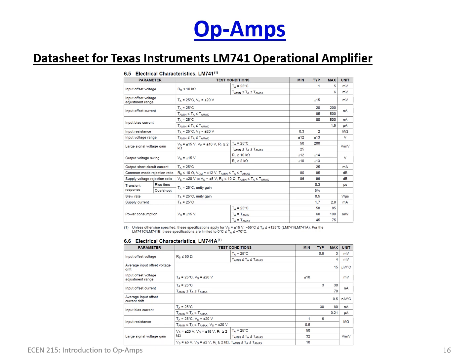Now, one thing I wanted to show you here, the interesting thing, and I'll blow it up here, is your input resistance. We talked about that a moment ago. Ideal input resistance is in the megohms, so typically it's 2 megohms. It's not infinite, but it's really high. It does talk about your common mode rejection ratio, which is really high here.